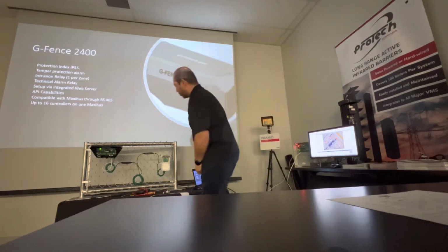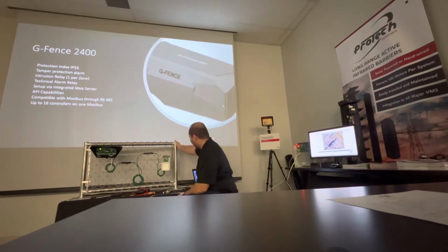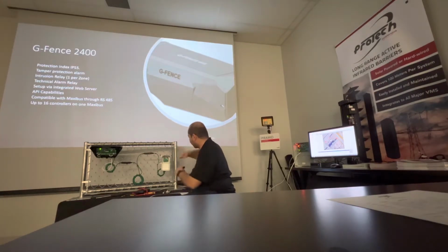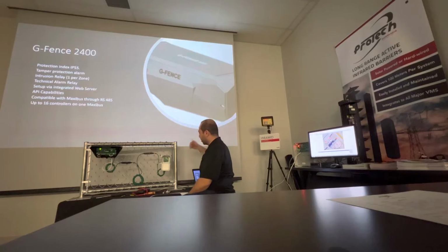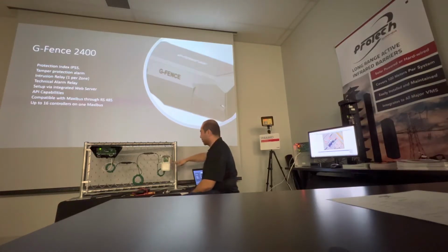And very important, so one control unit, one roll of sensor cable. You put one sensor cable on each panel, the other one on the second panel. If you face one metal fence panel, you have to make a small loop so the cable is not too tight. And when you reach the end of 100 meters, you have to use the link box. At the link box, you put the last sensor here, sensor number 40, and you start with 41, and you keep going with another 100 meters. Then you can cut the cable after 175, and then put your unit link. These cables come in different lengths, so they all have to be the whole roll. It's all 100 meters.